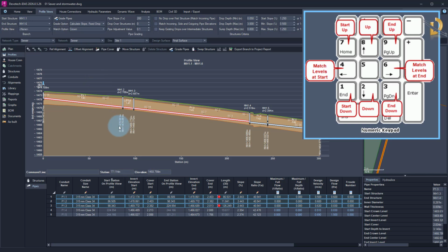And there's one more command which I would like to show you. If I move this path down, and let's say I want to match this path to that path, I have two options. If I press Control 4, it moves the red path up because the checkbox is not selected. So let me move it down again. However, if I tick this checkbox and I press Control 4, the black path comes down to the selected path. So this one allows to move non-selected paths. That's very important. Let me just do minor adjustments. So I have a network that actually works, maybe something like that. So these are grading tools improvements, and once you get used to it, it's very simple.